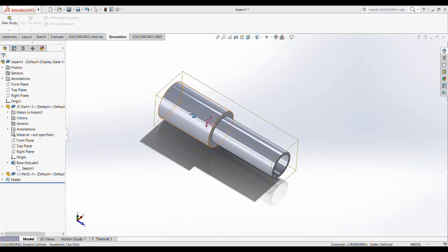Maybe it's better to go to the individual part and override the mass property of the part. So open the file of this part and play around, or there's a bunch of different ways. You can make it, like I said, thicker or thinner to hit that mass.